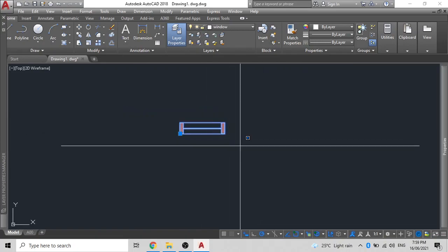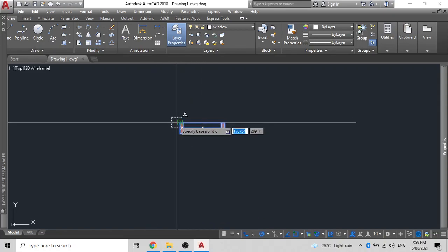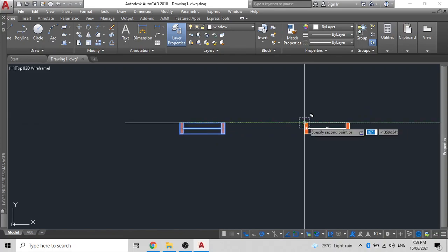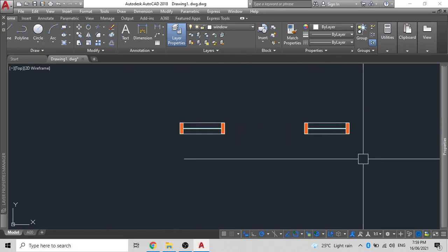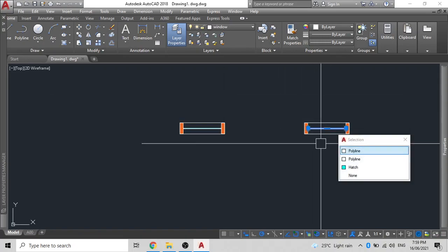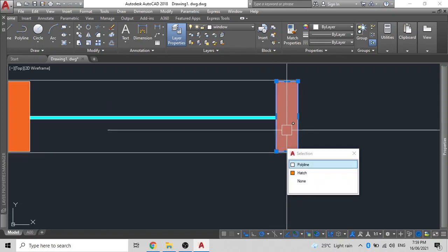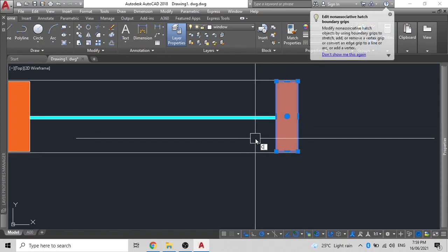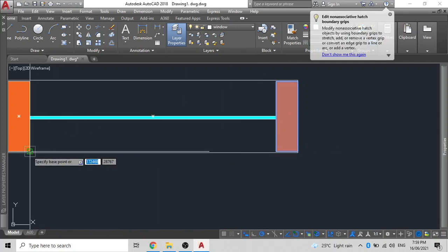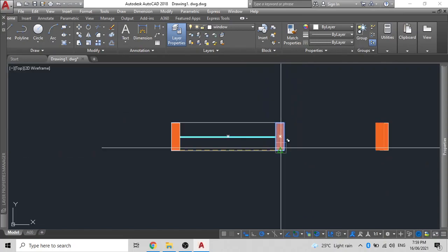Now the next thing, we do not have to repeat everything here. What we can do is just copy this, bring it here, explode, EXPLODE, explode the objects, and then what we can do is simply select these two, type CO for copy, and move this one outside once,